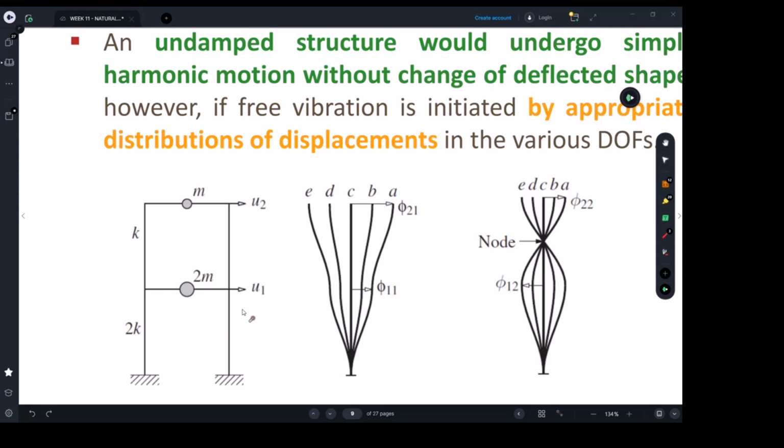It's got 2 as well, because we have 2 clearly defined masses in the system, which are the second floor and the first floor. We all agree that assuming we have a 2 degree of freedom system, then we have 2 mode shapes.